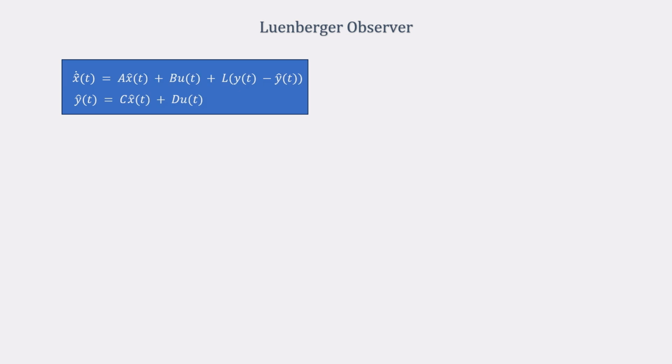So, again, this is another system, like for the open loop estimator, where we had created a system x hat dot equal to A x hat plus B u, y hat equal to C x hat plus D u. We had created a copy. In this case also we will create another system. However, the differential equations governing the system will be a little different. What is that little difference?